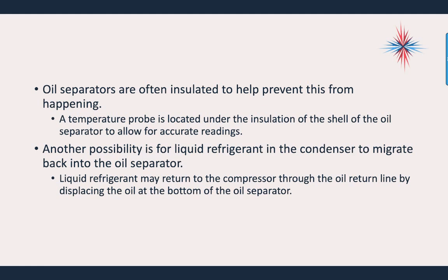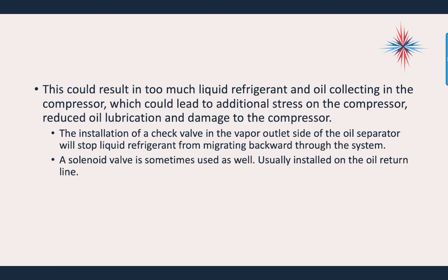Another possibility is for liquid refrigerant in the condenser to migrate back to the oil separator. Liquid refrigerant may return to the compressor through the oil line by displacing the oil at the bottom of the oil separator. And again, we have to remember our compressor does not like liquid. This could result in too much liquid refrigerant and oil collecting in the compressor, which could lead to additional stress on the compressor, reduced lubrication, and damage to the compressor.